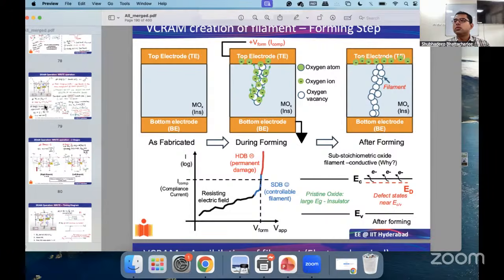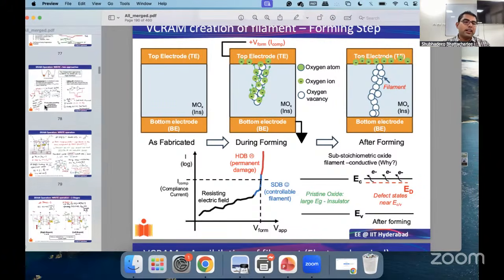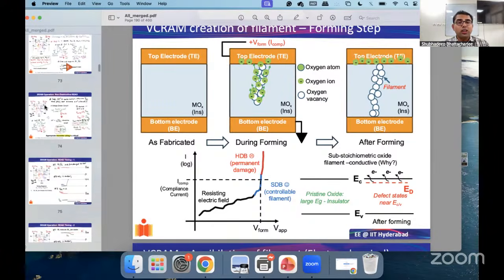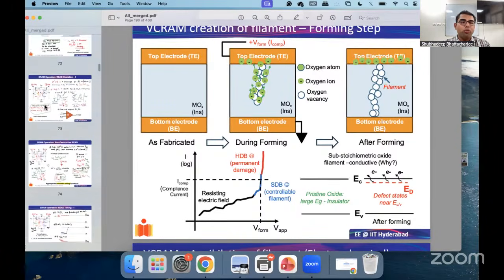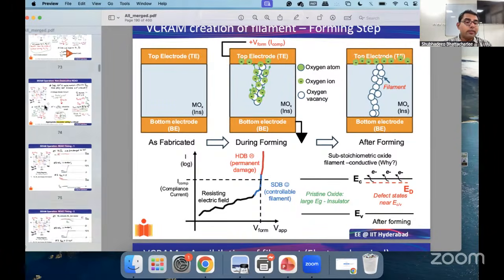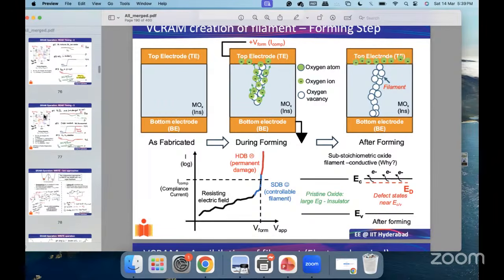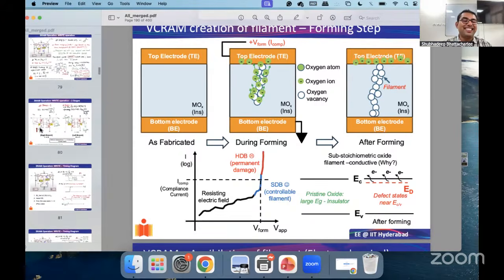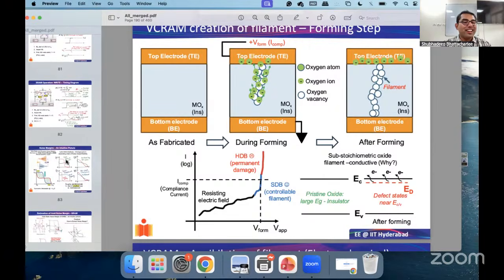Due to fabrication variabilities, the threshold voltages will be different. If you have a higher threshold voltage, it will be a slower system. So that is what he's referring to. Okay, I understand what you're saying. You mean the threshold voltage changes. Yes, VT changes. Thank you.